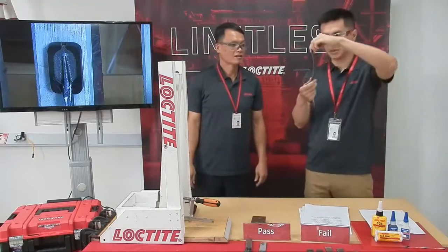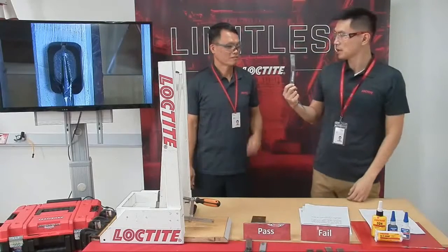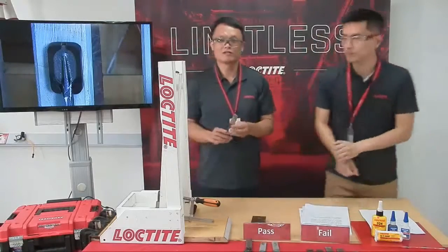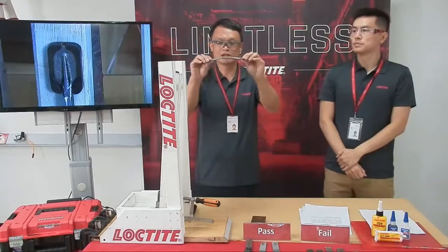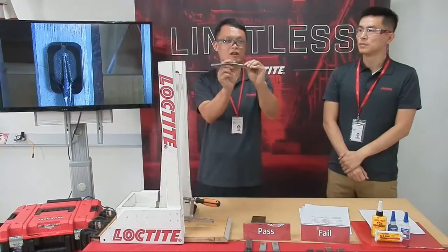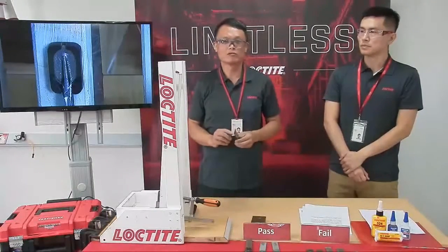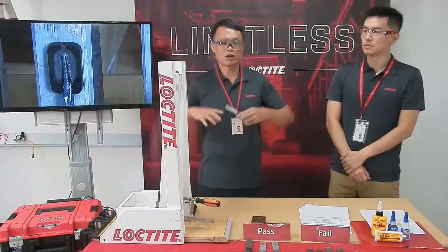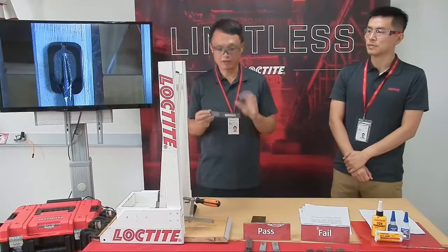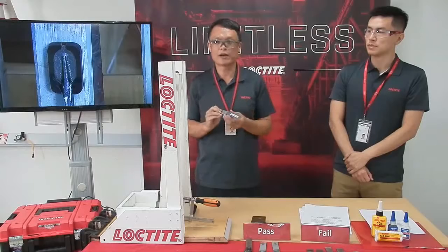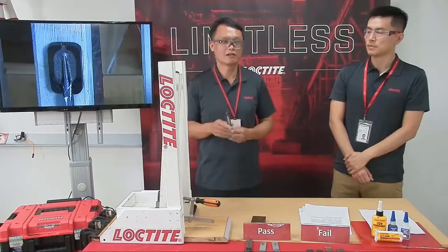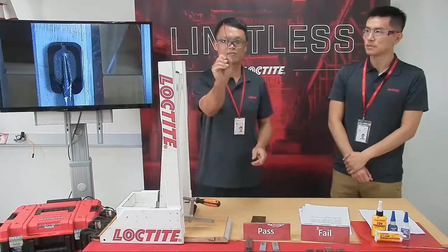Why with the structural acrylic do you see the distortion of the substrate? How can we explain that? The distortion of the substrate means that the energy has been absorbed by the structure other than the joint itself. From the structure point of view, this is a very good failure mode because the whole structure can absorb the impact loading instead of the joint taking the full impact energy. So it enhances the robust structural integrity of the whole structure design. So that's what engineers really want to see.